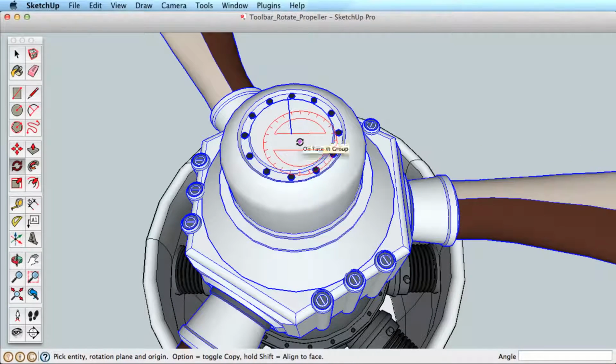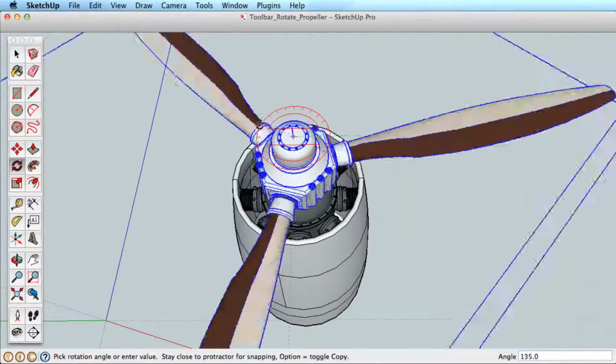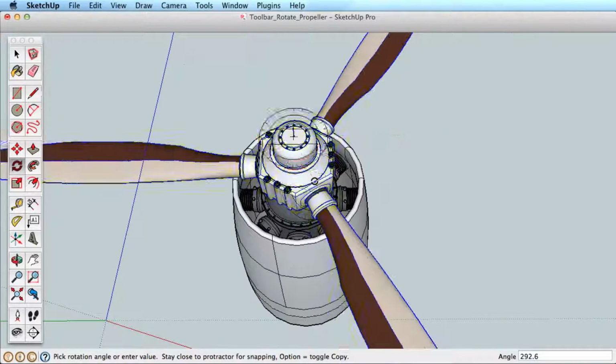Begin by selecting the object you want to rotate. Now click your mouse button once to set the rotation center and orientation. Then move your mouse away to establish a rotation arm and click again to rotate the object by that arm. Click a 3rd time to finish. That is how the Rotate tool works.